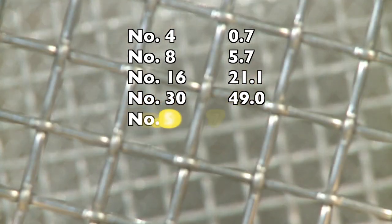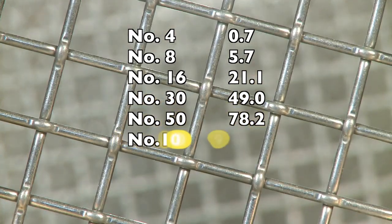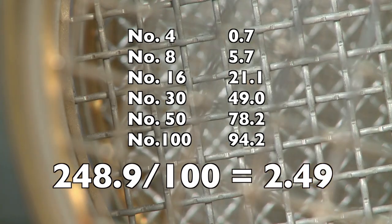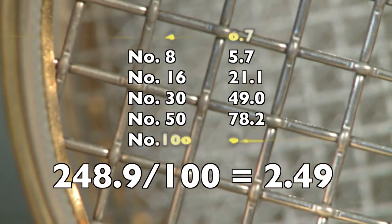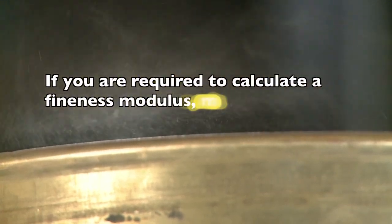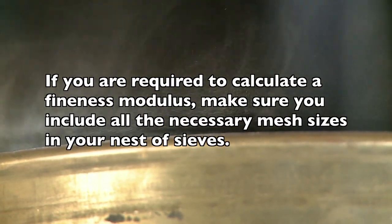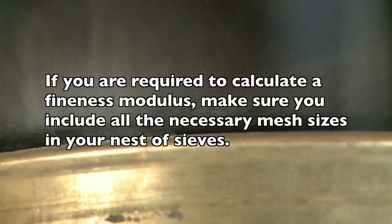For our fine aggregate example, the largest sieve in the series to retain any material was the number 4. So we add together the percentages retained from the number 100 through the number 4 and divide the resulting sum by 100 to get a fineness modulus of 2.49. If you are required to calculate a fineness modulus, make sure you include all the necessary mesh sizes in your nest of sieves.